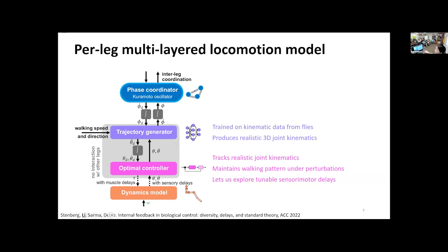Okay. What's the problem with just having the trajectory generator? What do you mean it does something weird? So let's say one of your joint angles is normally doing a sinusoidal wave like this. Now, if you add a perturbation or a delay and then keep using the trajectory, it's going to do like that. And then it's going to keep going. Well, sometimes it goes on, and sometimes it gets back. But it's like 20 degrees and then 200 degrees and then back, and it's not right. Whereas if you do the same thing with the controller, you just get a little blip and then you come back.